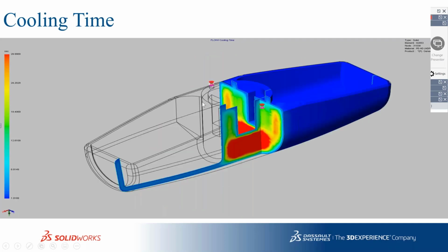And the cooling time, we can also see how much time it will take for the cooling. At this point, I would like to bring one more point. If we have the cooling layouts already designed inside SolidWorks Plastics and we have done the cooling analysis, it gives me the accurate cooling results. Otherwise it takes it on its own. The software takes some parameters, assuming that adequate cooling is already given, and it gives you the results. So there is a difference here.